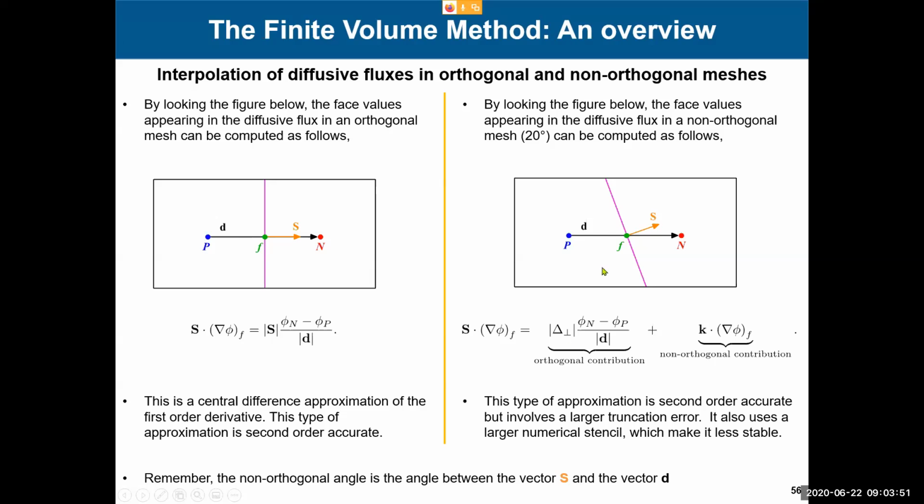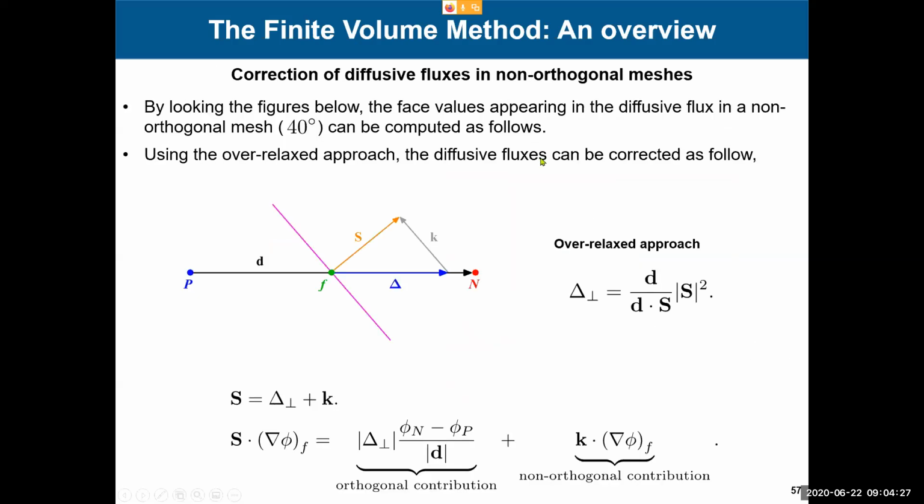And those are those famous corrections in CFD that sometimes are confusing. So the non-orthogonality is this angle, the angle between this vector S and this vector connecting the cell centers. So you see that if this angle becomes 90 degrees, the cell volume is 0. And that's why we always run checkMesh and check your mesh quality, okay? If you are close to 85, probably it's a good idea to refine the mesh, because we know that this will have an influence on the gradients, and the gradients, we have them all around in the approximation of convective and diffusive terms.